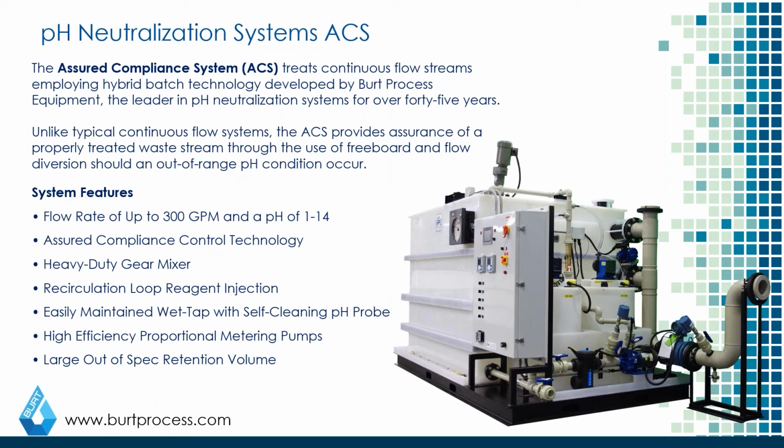Another thing to consider when building a containerized system is access to the top of the tank and access to be able to remove things like agitators from the tank, as well as the ability to access pH probes or other instrumentation that goes into the large treatment tank. This all plays into why the ACS design, with its ergonomics for circulation and the lower level access that you can see here in the image on the right, becomes very critical for these types of systems. That's one of the main driving points that people look at, which is why it's often utilized in containerized systems.